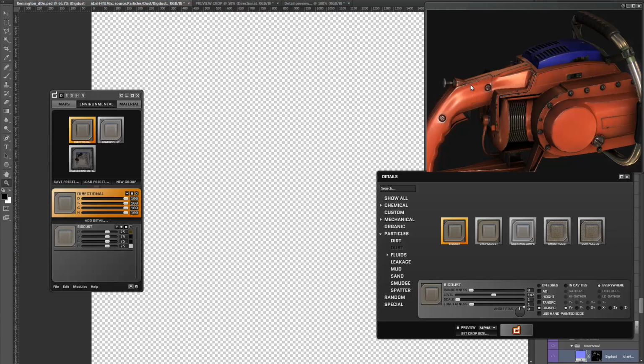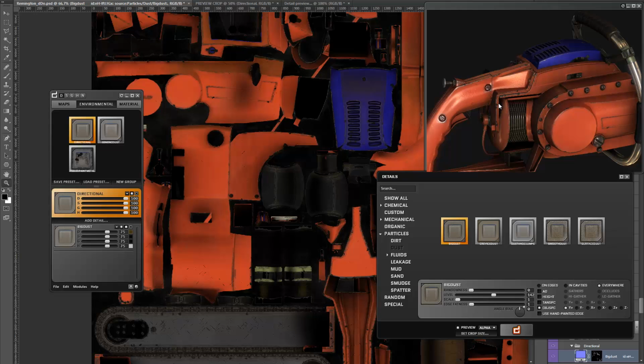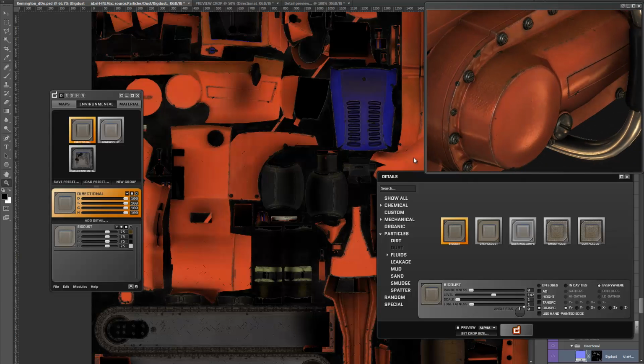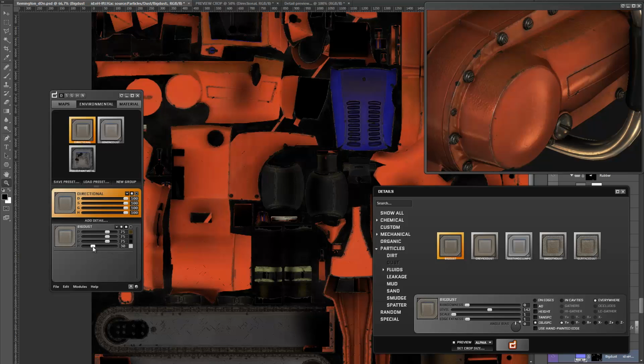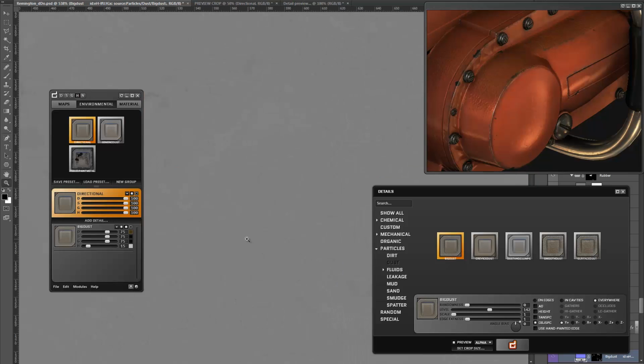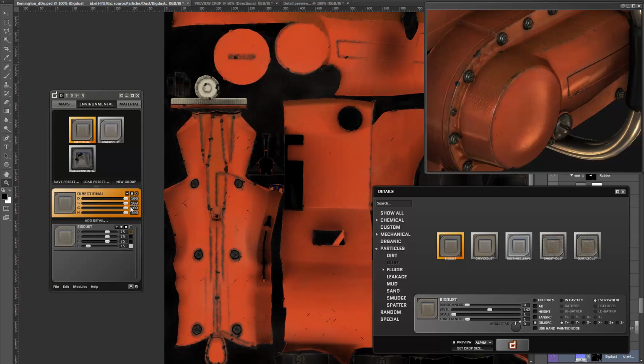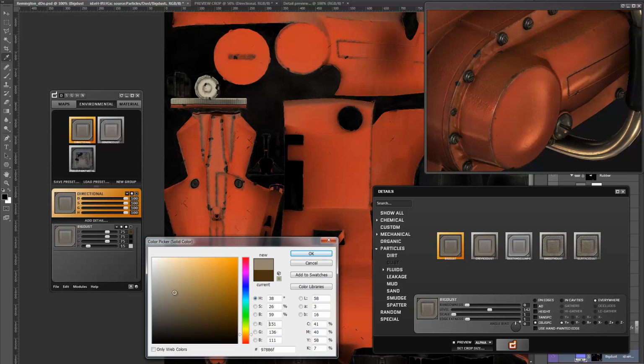And now it's saving out so I can preview it. Looks really cool. I'm gonna disable the auto refresh, and I'm gonna drag down the height information because it's a bit too extreme for my taste, to around 15%. And I'm gonna change the color a bit so it pops out a bit more. I want it to be a bit brighter. So I click the swatch here next to D, which stands for diffuse. Something like this.